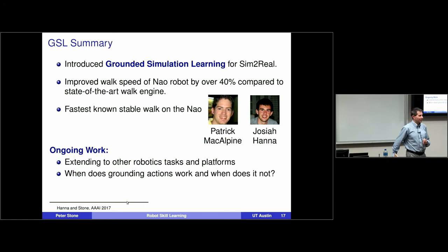Pick some intervals of variation for the center of gravity and run those N trials and then pick the one with the best performance. It's kind of a backhanded way of asking, why can't you get the robot to stand fully erect with a higher center of gravity and move faster?